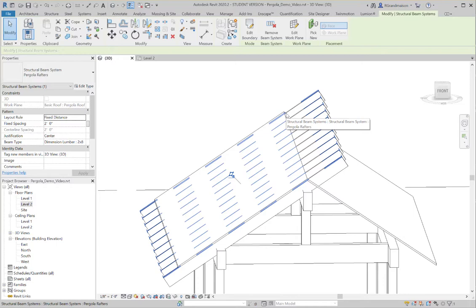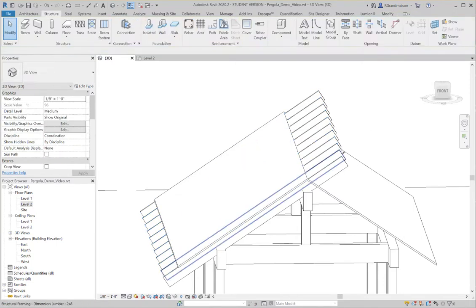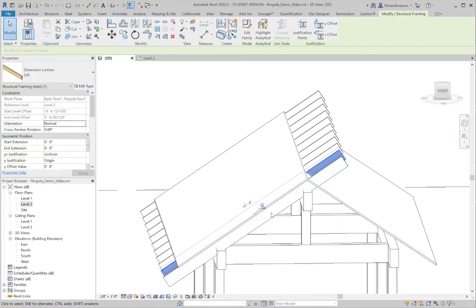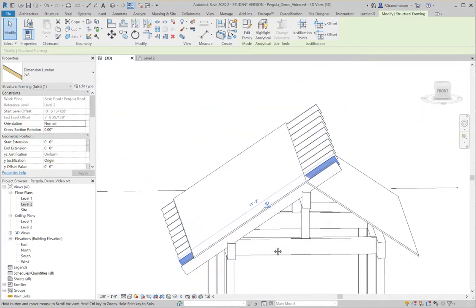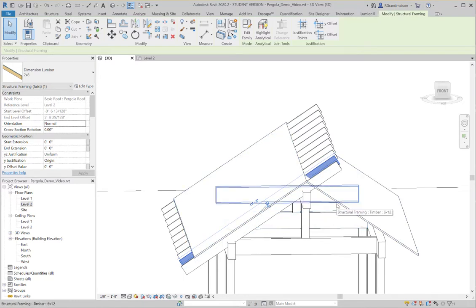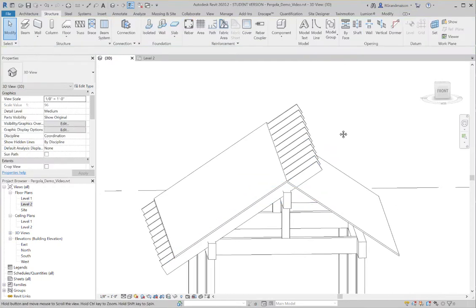And if you move this beam system, it moves all of the rafters for you. So you don't try to move the rafters. In fact, if you select one of the rafters, you'll notice it's pinned. So it's technically part of this beam system, and it moves with the beam system. If you wanted to disengage it and copy it perhaps, or move it around, like I'm going to eventually have to copy one to the outside maybe. Maybe not. I'll see how the rafter's laid out. That's when I can just copy it this way, but if I wanted to edit it beyond that and move it around further or customize it in some way, I would need to unpin it first.